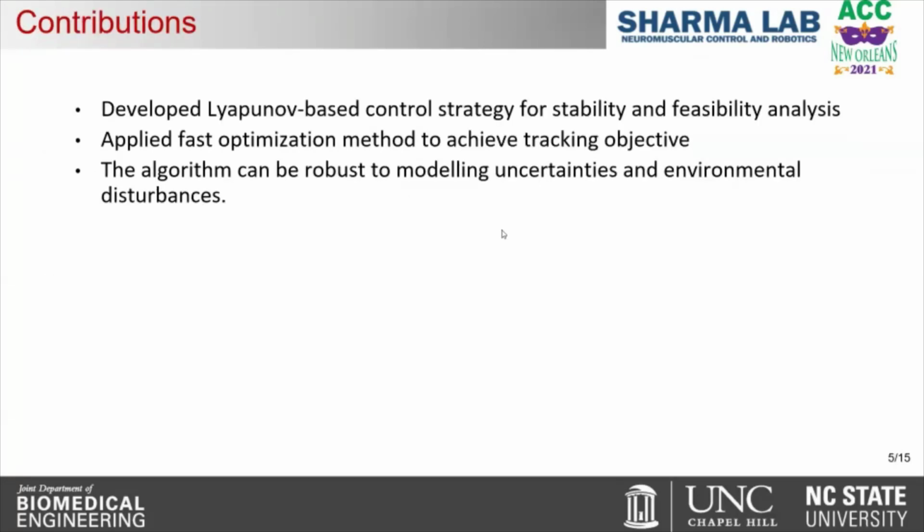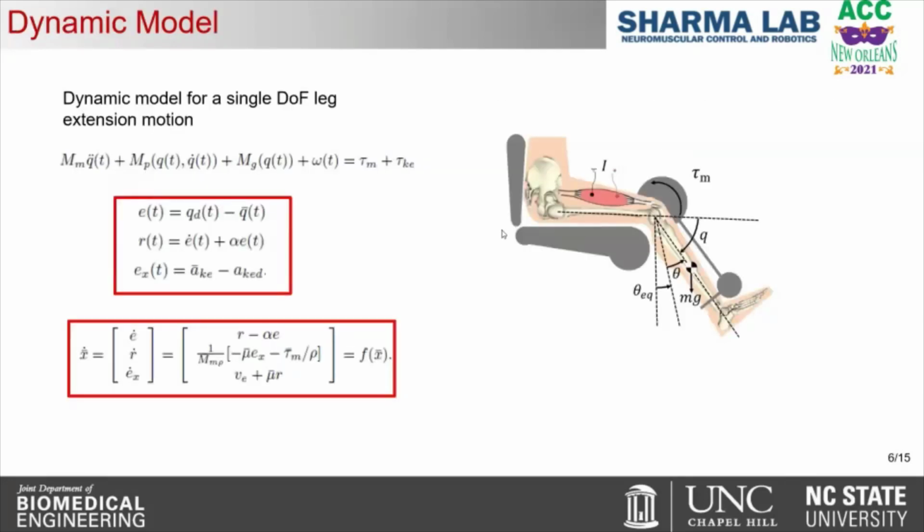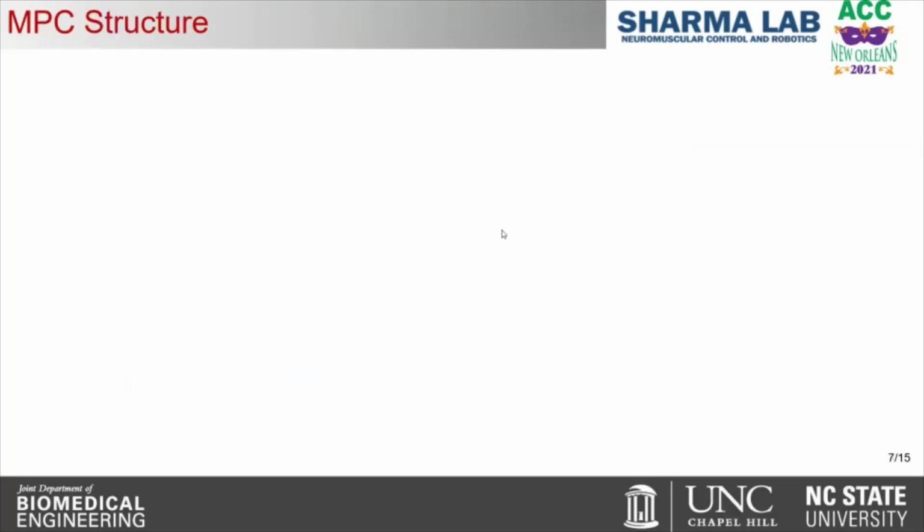To address the challenges of FES control and distinguish from previous MPC controllers, I designed a terminal controller that used the Lyapunov-based control strategy for stability and feasibility analysis, applied a fast optimization method to achieve the tracking objective, and can be robust to modeling uncertainties and environmental disturbance. This is a single degree of freedom leg extension model, and the model is controlled by motor and FES. The control objective is to let the extension angle track the desired trajectory.